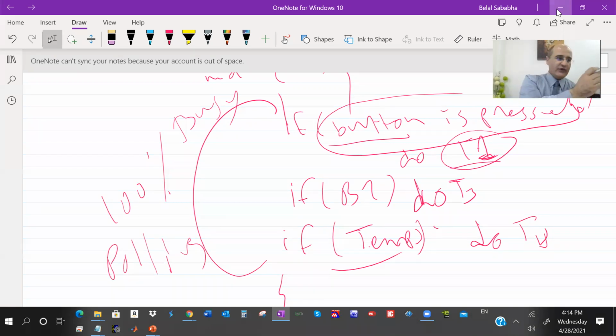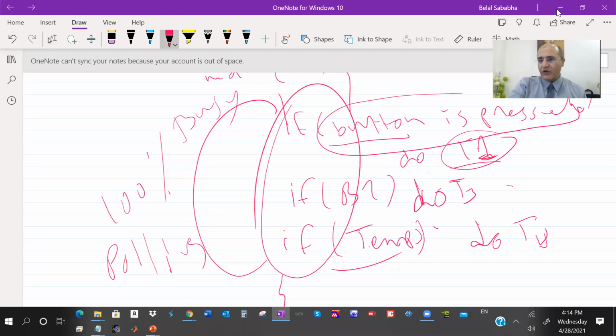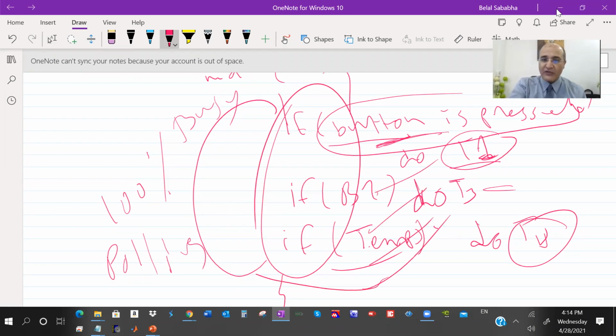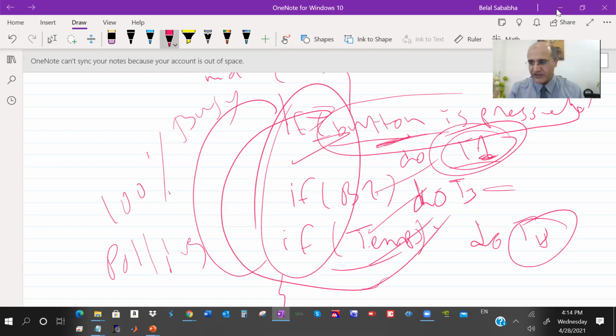Then when the last one is done, you go back. So here, maybe a low priority task can waste the time of everybody else. The CPU is busy. Imagine you check this button, it was not pressed, then immediately when you leave this condition, this is true, this is true, this is true, then the amount of time you're going to spend before returning to this task service is going to be a lot. And this will not be helpful in real-time systems.